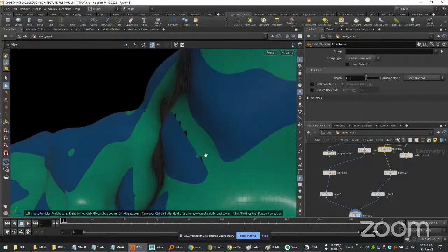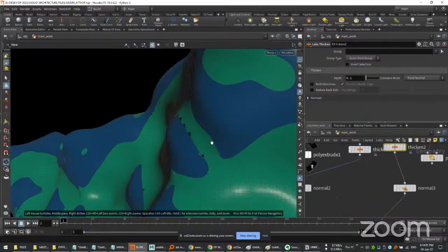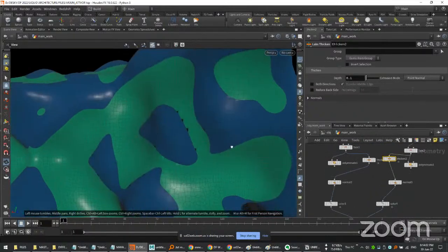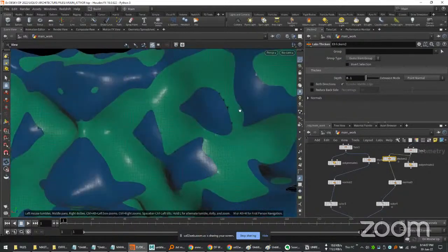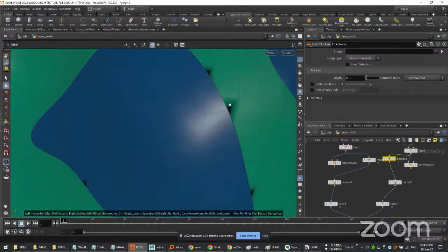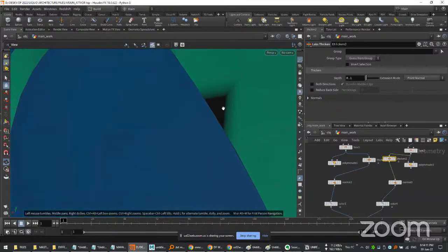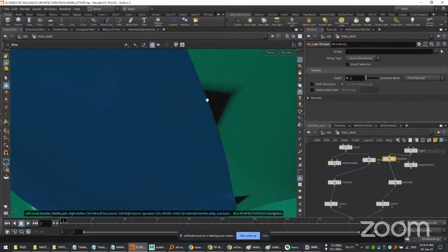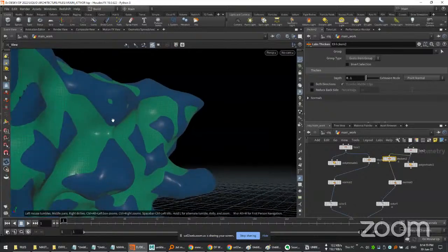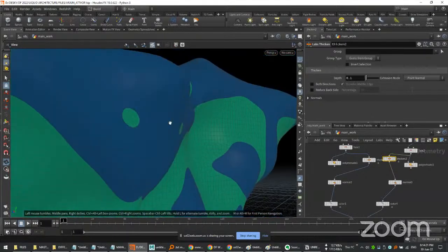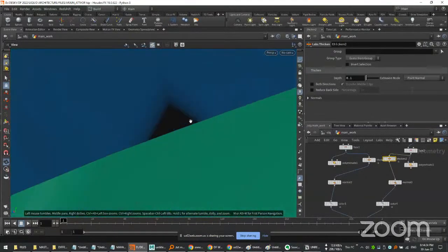So, like you advised me to use Thicken instead of Polyshoot, so things came out pretty well. But the only issue is I don't know how. I think they might cause trouble in textures. They might get bent. So these bent weird faces are appearing at the junctions. Although overall it looks decent, on close-ups there are some issues like over here. So how do I fix this?